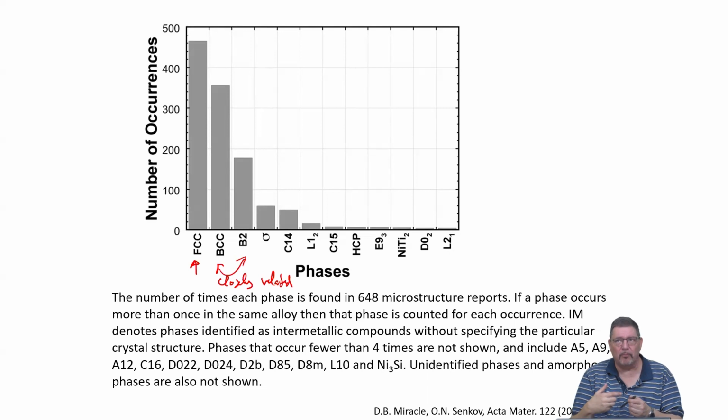And this will most likely, especially if I add several elements that have the same structure in, result in structure out, the structure of the phase of the solid solution that forms when mixing them. And so this structure in, structure out kind of thinking seems to be fulfilled for many high entropy systems.